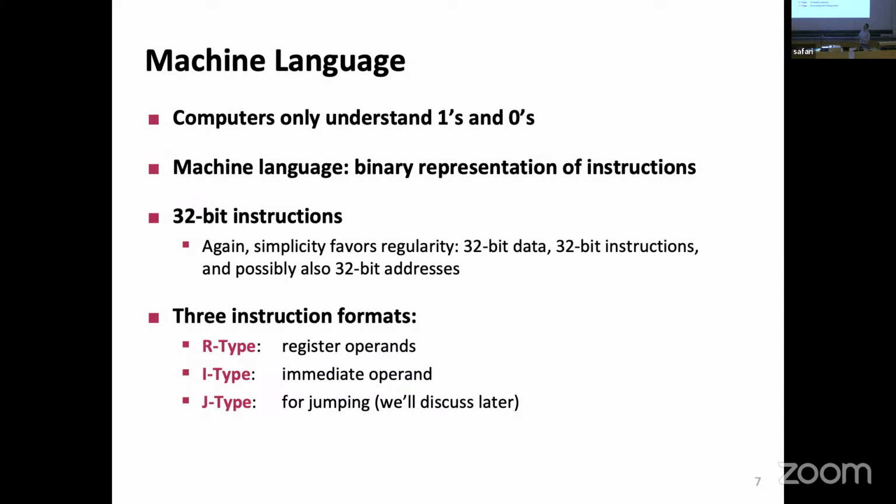That was a choice that was made by the designers, and they said, I want to have some design principles. I want to keep things simple. I want to make the common case fast. And instead of having a lot of complex instructions, I'll just use the very minimum I need. I'll implement them well. And if I need to do something a little bit more complex, I'll just use a few of those instructions. On average, I'll be winning because my small instructions will also, most probably, be efficiently implemented in hardware. I can do things very, very fast.